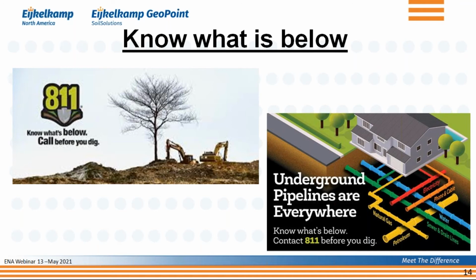I've taken some pictures here from posters that are being utilized in the United States where you can dial 811. Around the world, it may not be the case, but the message remains the same. Underground pipelines are everywhere. Underground cables are everywhere. So know what is below before you start your CPT, because obviously those things can go wrong or can cause problems, and you want to avoid those.